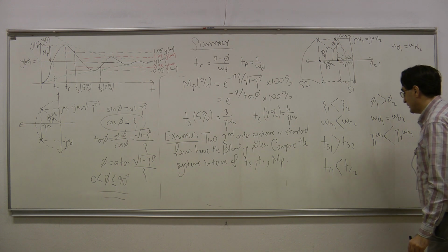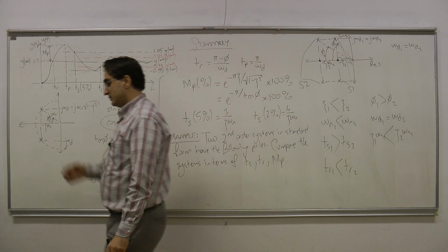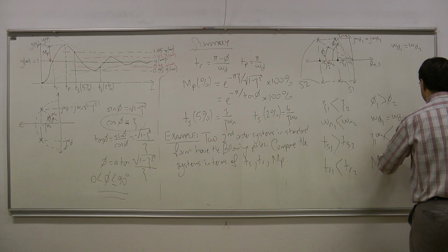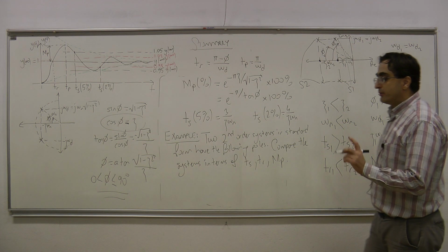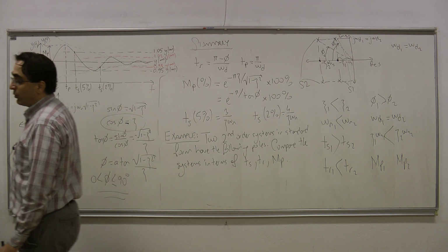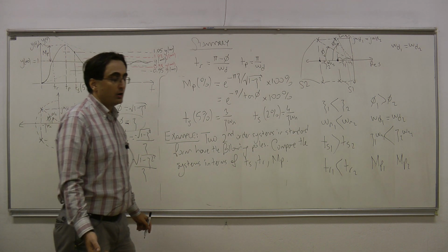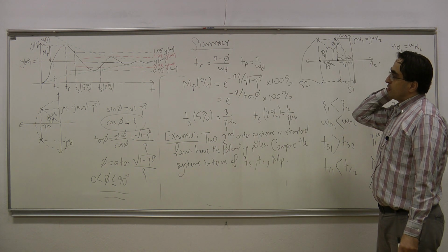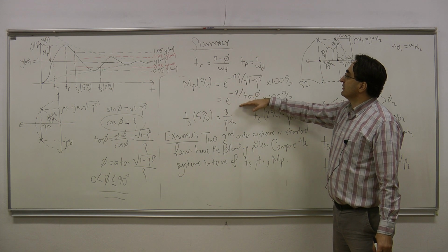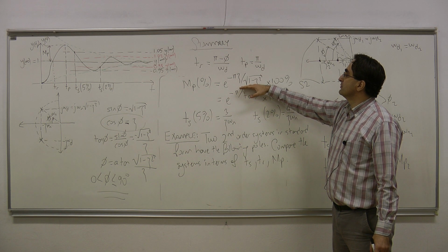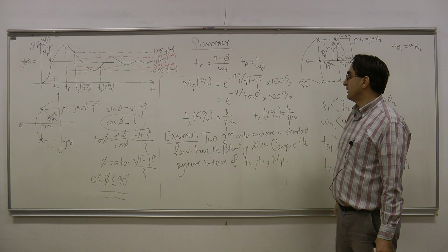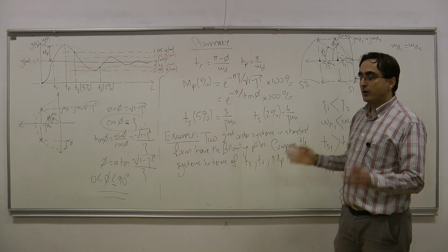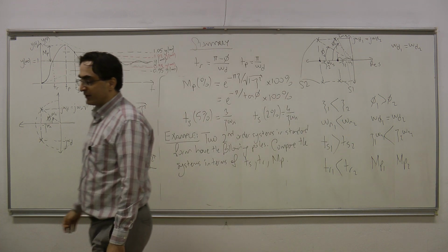All right? And finally, I come to the maximum overshoot, Mp1 and Mp2. I know that the maximum overshoot is only dependent on the damping ratio or the angle of the poles here. So here, these are the expressions. I have the damping ratio relationship given like this and the angle relationship given like this. In my opinion, if you try to use these expressions, you are going to almost always make a mistake.